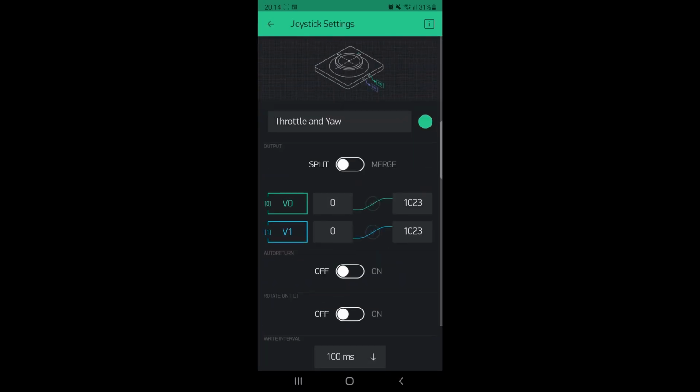And here you guys can see what we did in Arduino code, where we spoke about the virtual numbers. So V0, V1, where we had blink right and things like that. And this is the number I spoke about, 1023. So this is the input that my Arduino or my ESP32 is going to get. And then I'm going to map the values to values that I can use. So for the throttle, we map it to 2000 because our PWM resolution is 11 bits, so we can go up to over 2000. So we cap it at 2000.